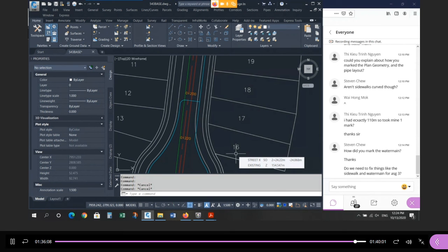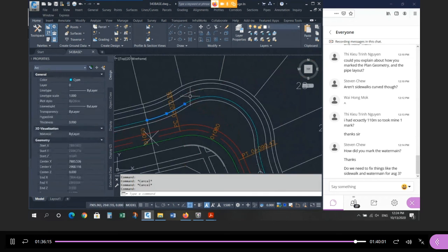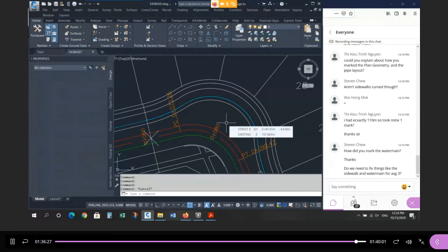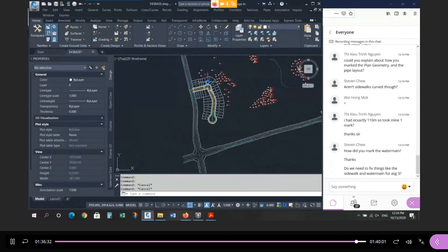That water main one, that's a cool one. I really like that one. Where do you draw the water main? And there's more to it. The water main over here, this is wrong. This is not going to happen in reality. These radii are too tight for plastic pipe. If you try and bend the pipe to those small radii, it'll break. How do we deal with that? Next semester. Okay, it's beyond the scope of this course right now. Okay, so that's all I want you to do.